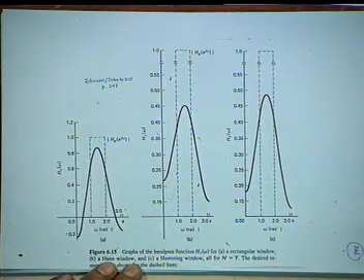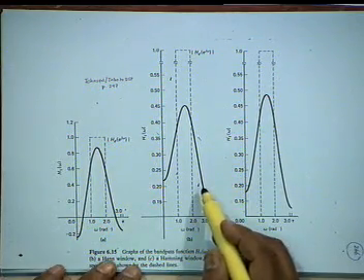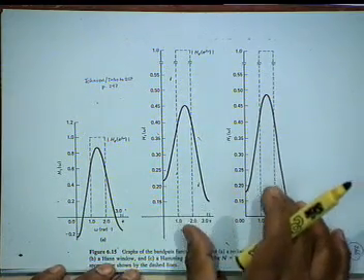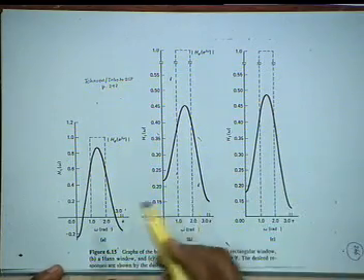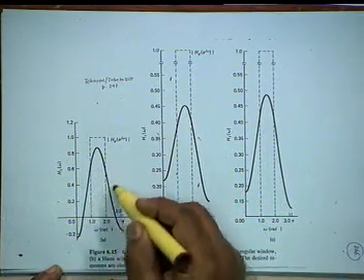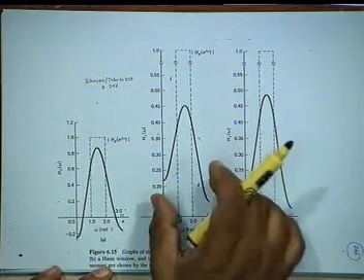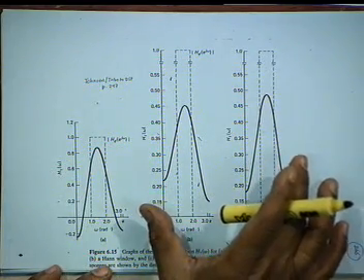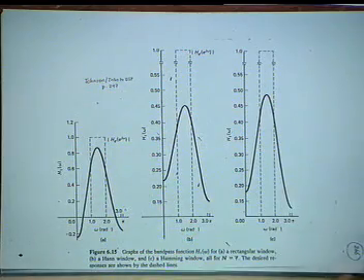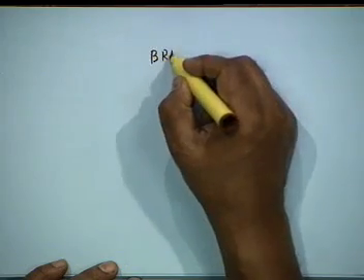So, in the rectangular window invariably the pseudo magnitude does go negative; with this it does not, but it is not very discernible here. But if you calculate the slope of rise and slope of fall, they are sharpest in rectangular. What you pay here is a widening of the bandwidth. As I said, capital N equal to 7 is a very small number and it cannot achieve any useful purpose. Finally, we look at the band reject filter.